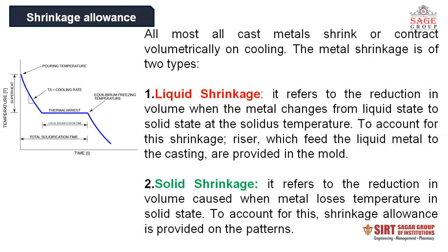It must be noted, it is worth noting, that the liquid shrinkage is not compensated by the shrinkage allowance. Shrinkage allowance only compensates the part when the metal solidifies and comes to room temperature. That shrinkage is covered by the shrinkage allowance.